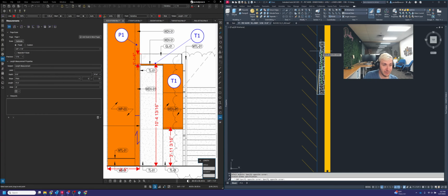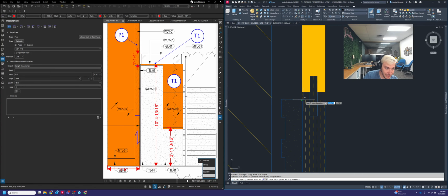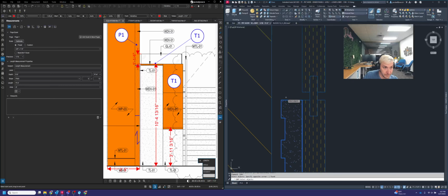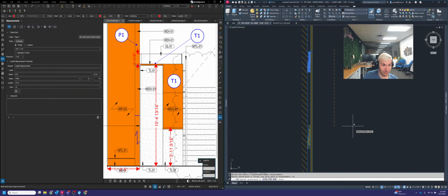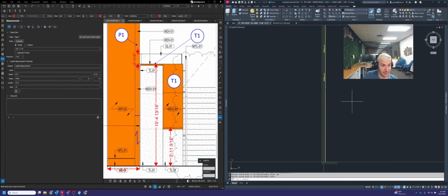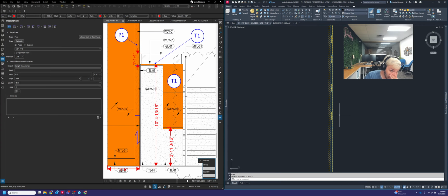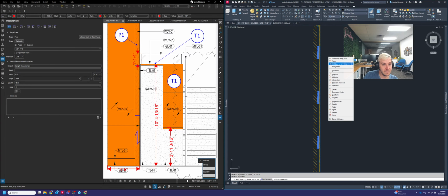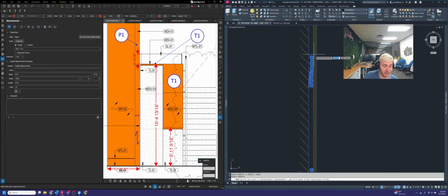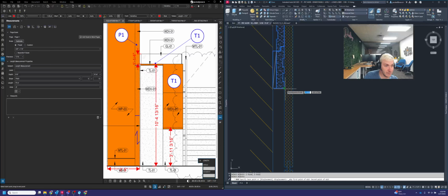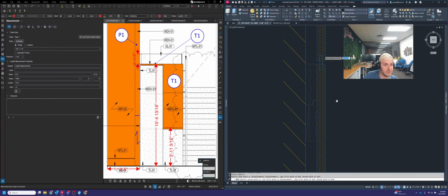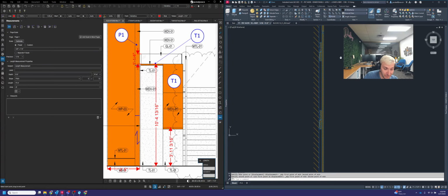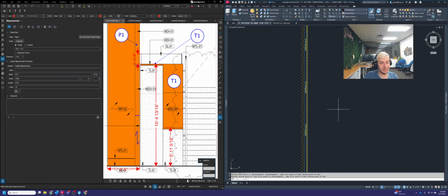Again, same method of approach. We are going to copy a cleat down to here. Copy this down 24, copy this down 48. Looks like we can, oh, no, I guess there is one more panel below this one. I'm sorry. We got one more to go. So let's move these. Shift right click, mid between 2 points. And shift right click, mid between 2 points. Sorry, I get lost in the zooms sometimes. There we go. That's better.